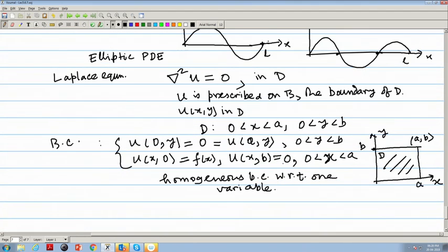For the time being, we assume the situation given by this elliptic PDE, also referred to as the temperature distribution equation. Say a certain slab is heated to a certain temperature, the boundaries are maintained at a fixed temperature, and heat diffusion is in progress. At any position the temperature inside the domain is governed by the Laplace equation.